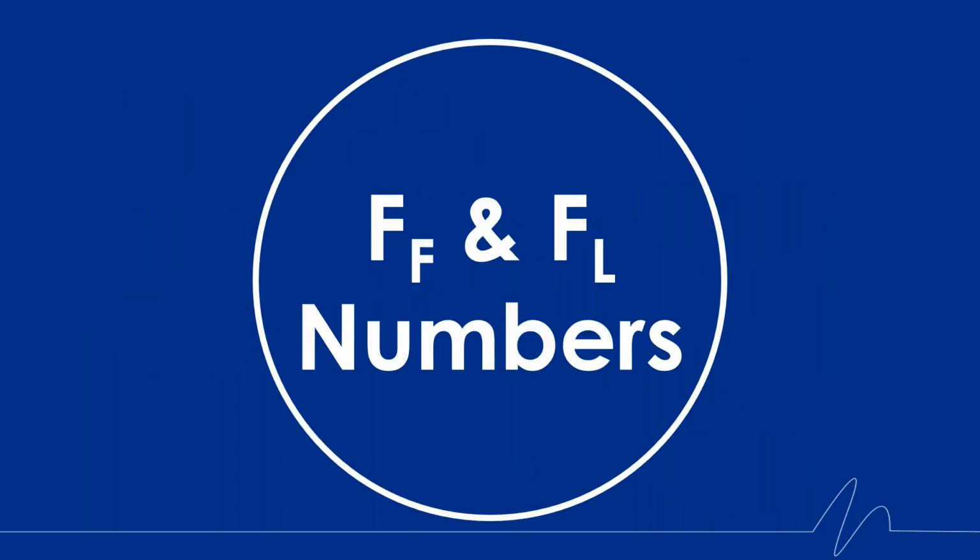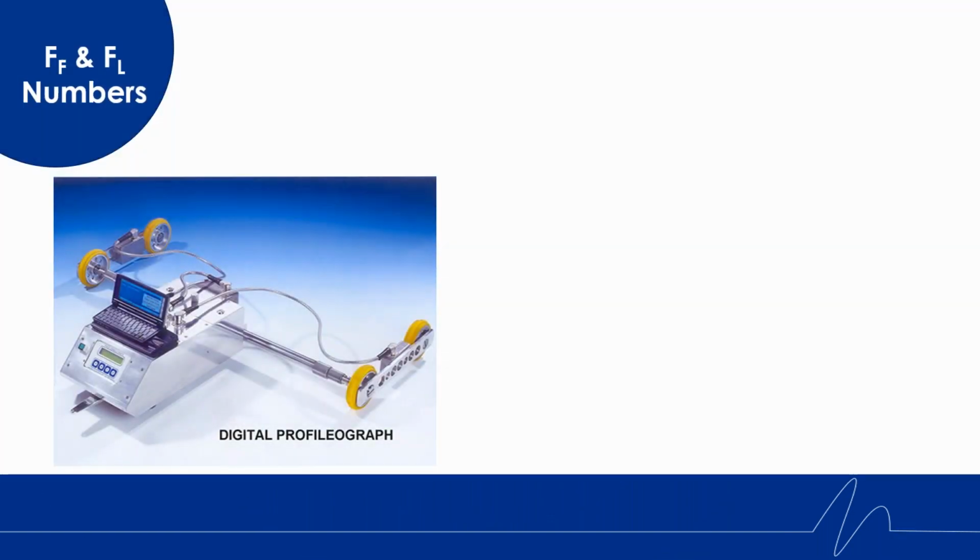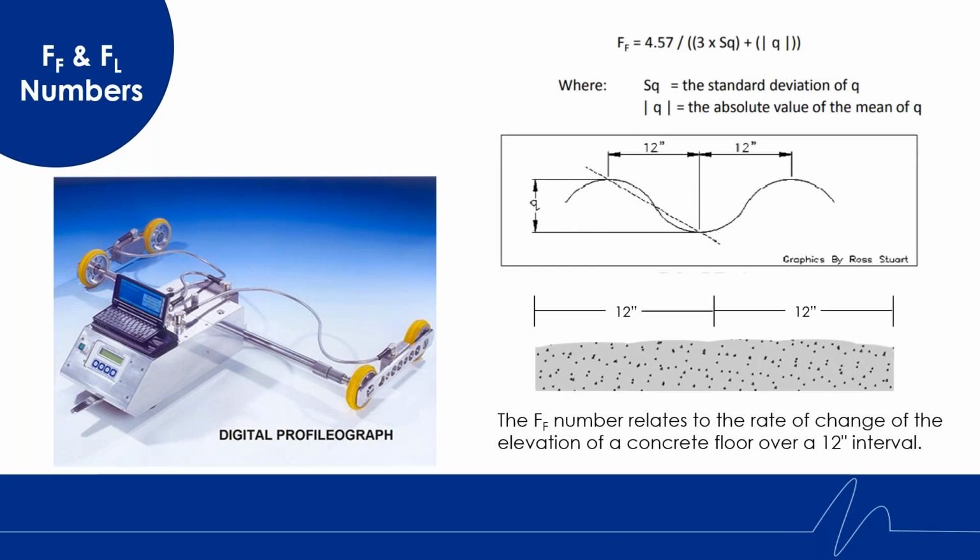So what are F sub F and F sub L numbers? F sub F and F sub L are numbers that relate to the flatness and levelness of a structural floor. These numbers can be acquired through a digital profilograph. Consult the manufacturer's specifications for proper usage. The readings are acquired from 12-inch spans of the structural floor, measuring from the high points to the low points.